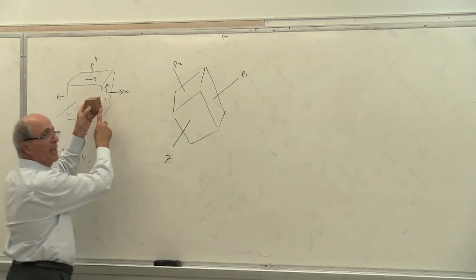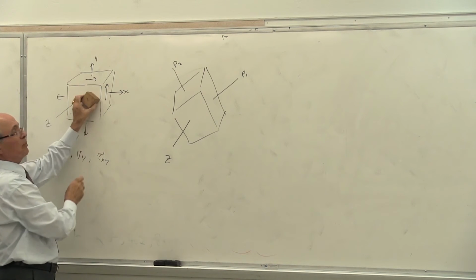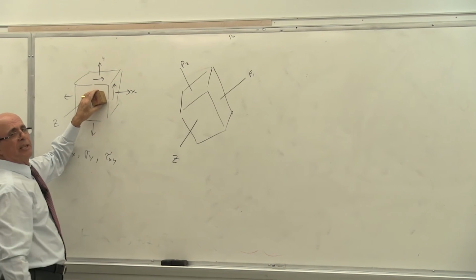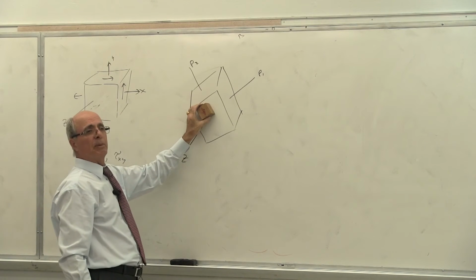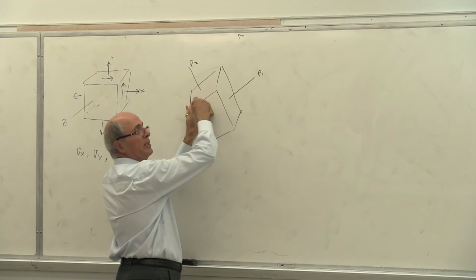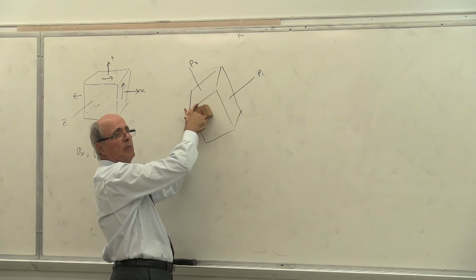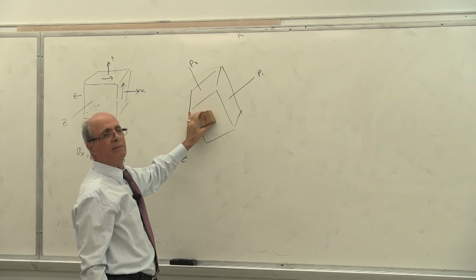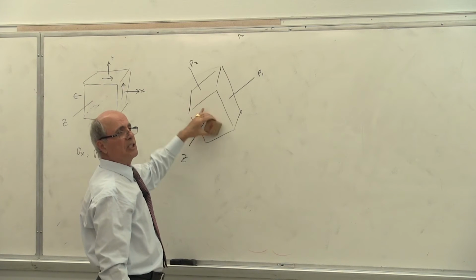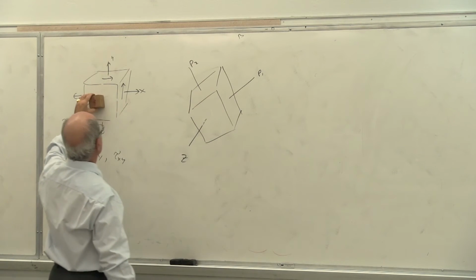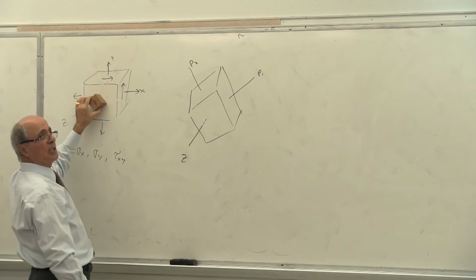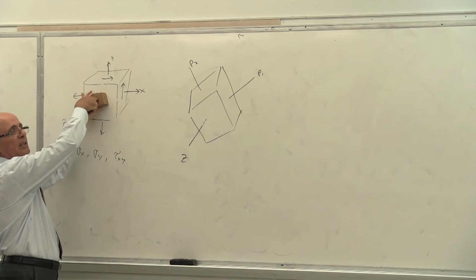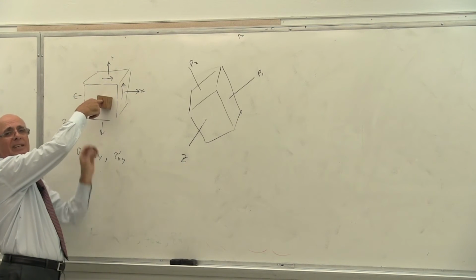Is this a stress there? Yes? I went this way to get rid of shear stress. Yes or no? This is now principal stress. This is principal 1. This is principal 2. Obviously, this is principal 3, but it is 0. Yes or no? Correct? But what rotation is this? When I want to go from this system to that system, what am I rotating now? Look at rotation about the?